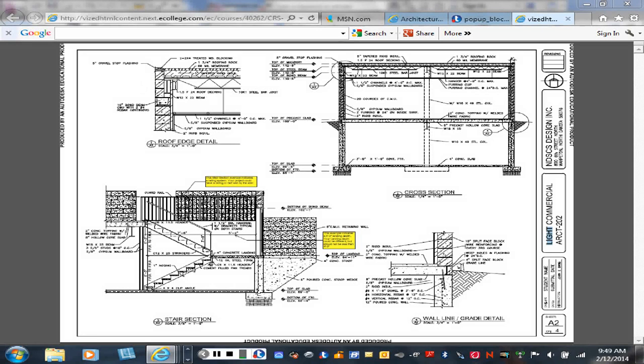Now, steel bar joists are different than wood joists in that typically they are top chord bearing bar joists. Okay? So they hang off the top of the beams. And we'll talk about that more when we get to drawing our sections, but the height of the bearing point of a bar joist depends on the depth of the bar joist and the length of the bar joist. But for this building, due to our less than 30-foot spans probably, that height of that bar joist bearing is going to be 2.5 inches. That's pretty common up to a 30-foot length. And then once the lengths get longer than that, that height starts getting bigger. It might be 4.5 and 5.5 and so forth.